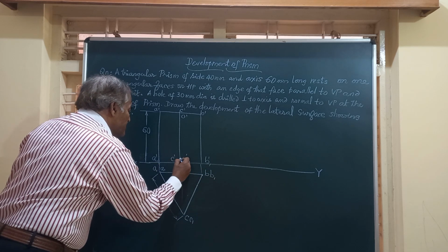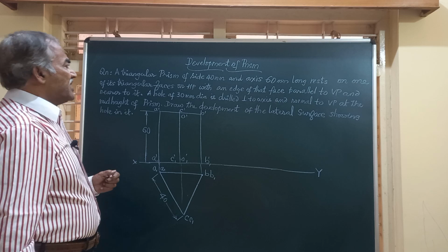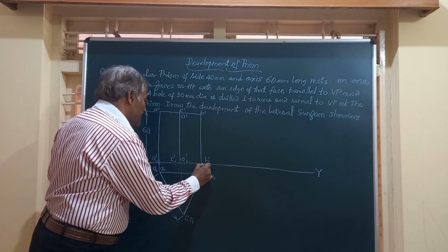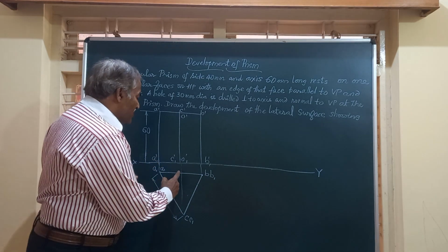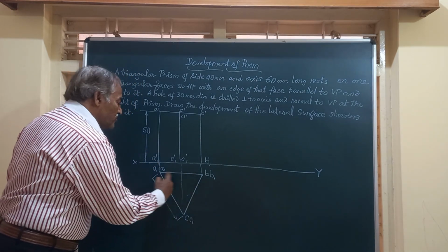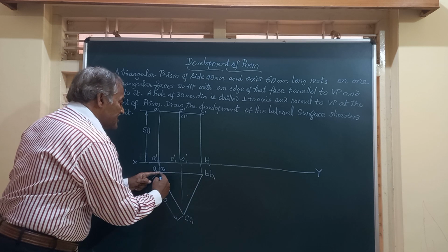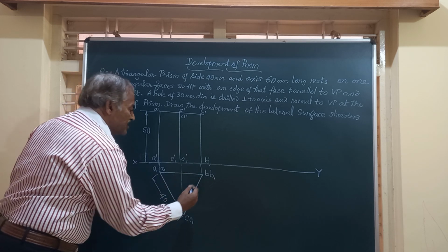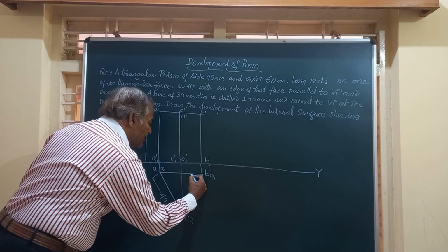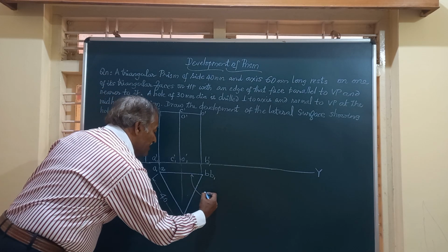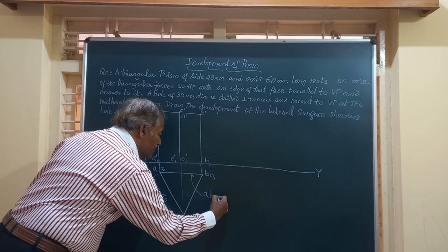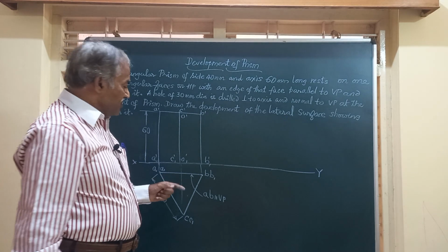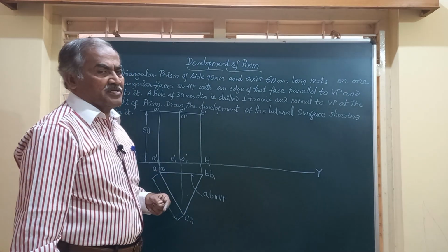This is the position of the solid, the triangular prism, resting on its base A1, B1, C1 on HP, with one of the rectangular faces, because this line represents the side AB, parallel to VP. I will write here AB parallel to VP and nearer to it, with one of the corners away from it.